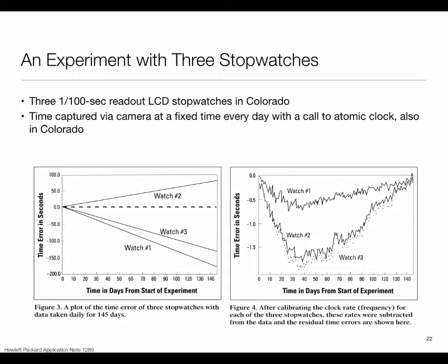What you see are your usual digital watches, and of course, if they had maintained the time as per UTC, it would have been stable, but the three watches did very differently. If you look at time in days from the start of the experiment, you see that they wander around quite a bit. It's not that there is a constant frequency difference. This frequency difference itself is varying quite a bit. And so the time error in seconds, at times it grows and at times it falls, and all of it is because frequencies are changing because of a variety of factors.